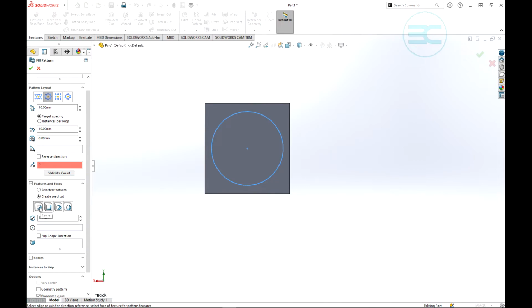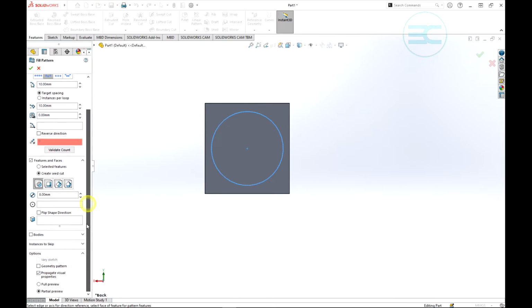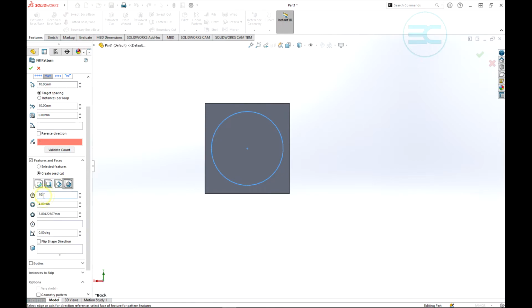You have option of circle, square, diamond, and polygon. So let's go ahead and have a polygon of let's say 6-sided, and also we can have outer radius of 4 millimeters. Then we can also have inner radius of that length. Then these ones are now okay.